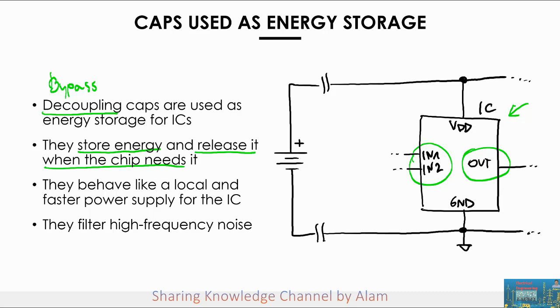The other two pins that you're going to find on any integrated circuit are the ground and the power supply. These are the two pins that you have to use to connect the chip to a power supply source at a certain voltage. And these are obviously required in order for the chip to work. Without a power supply, the chip won't be able to work. Now, ground is usually indicated with GND, so it's pretty self-explanatory, while the supply is usually called VDD; it could also be called VCC. It's very often the case that more than one pin is dedicated to ground and to VDD.